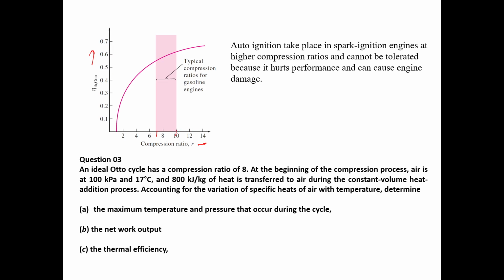There are some very rare engines, some direct injection engines, that have a compression ratio up to 10, but most of the time you have around 9.5. Most engines have compression ratios of, let's say, 8.5 to 9.5.